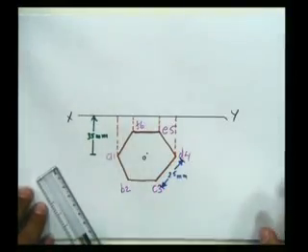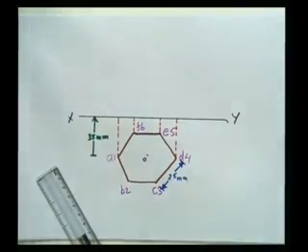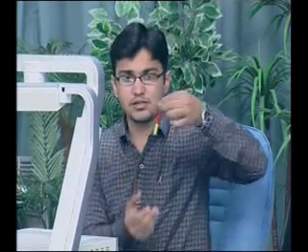Now it has been said that it is resting on HP. So when I am looking at it from the front, say if this is the pyramid that I am talking about and this is the tip of the base and it is resting on HP, then the base is exactly on the XY line itself. So the height is 45 mm. This tip that my finger is on will be exactly 45 mm away from this XY. So my height of 45 mm will exactly start from XY.